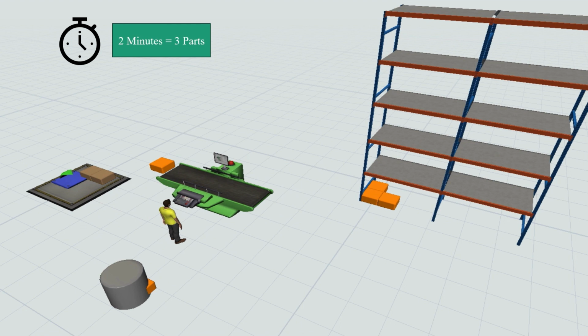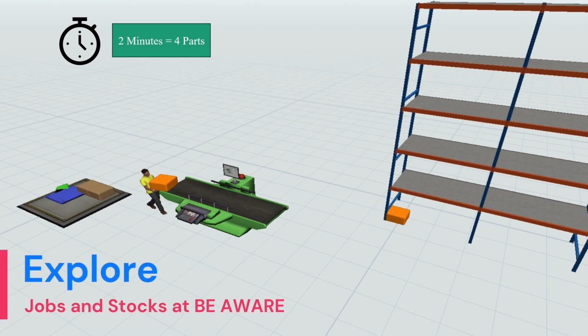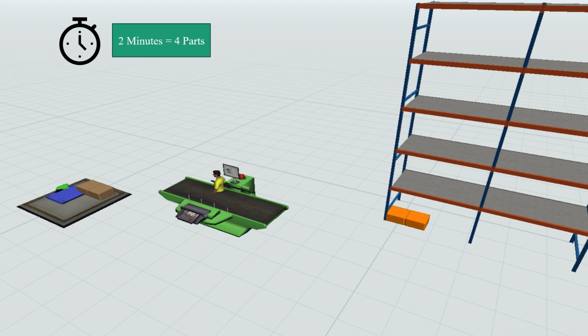After we do a work study and analyze the problems, or the activities which are creating non-value addition to the system, what we have done in the next model is eliminate the additional process which was creating non-value addition, and both activities are now done on a single station.